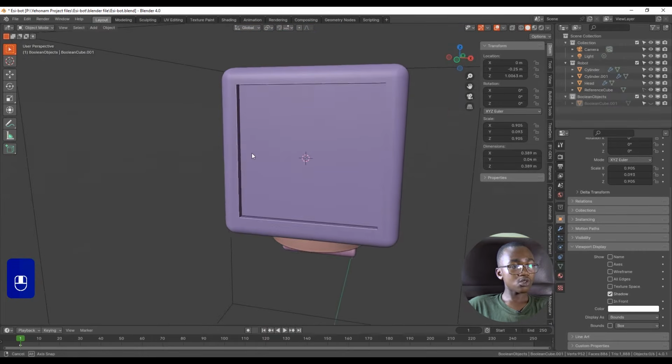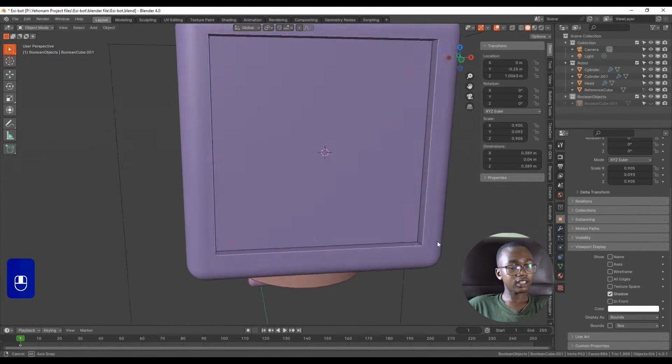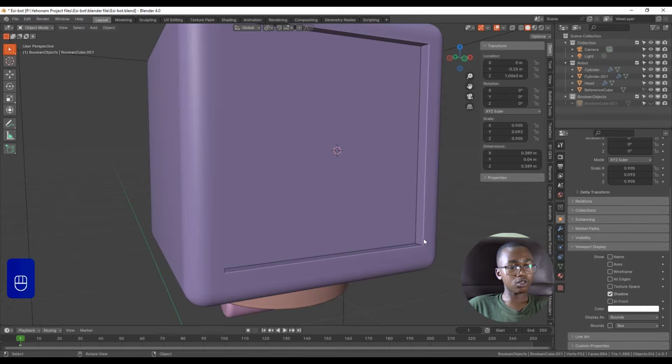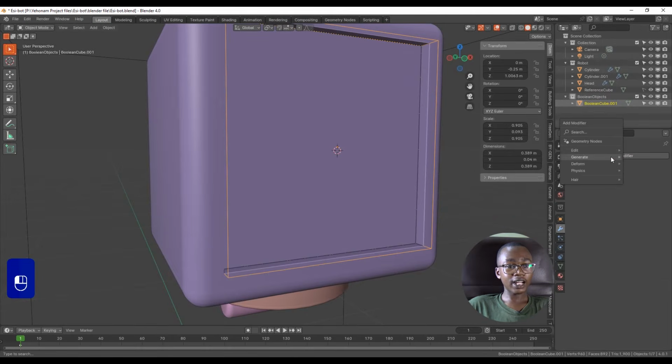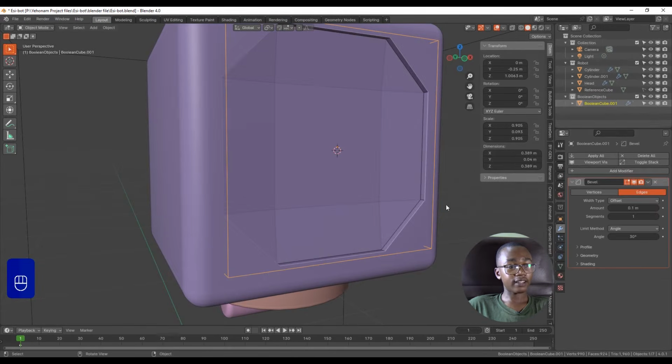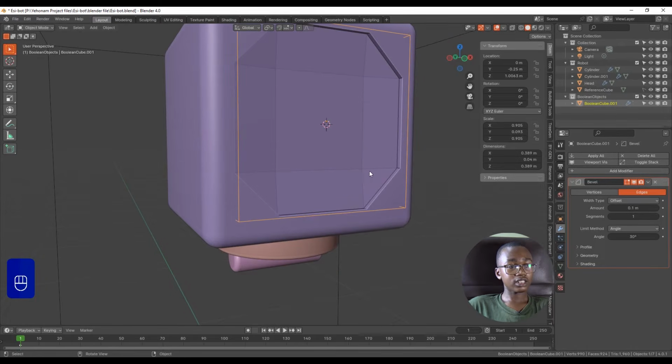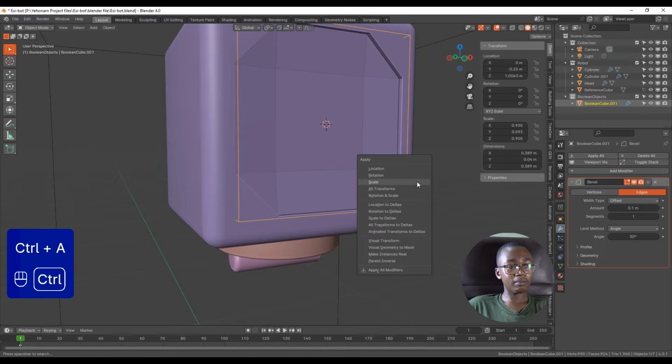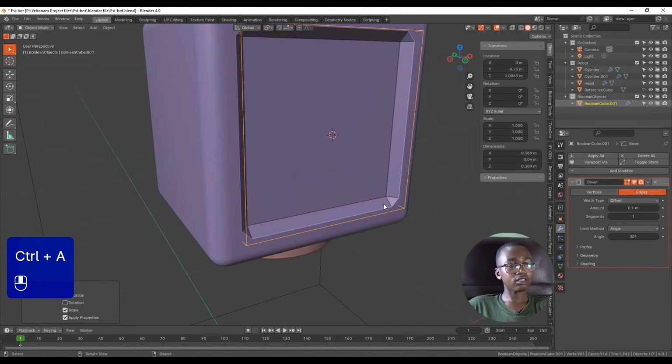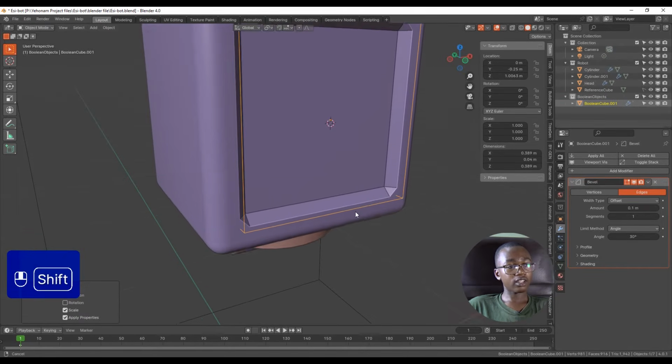I like what it's doing here, but I also like some sort of crease, you know, when it's meeting 90 degrees like this, at times it's not satisfying. It doesn't look nice. That is my personal preference. So how do we do that? You unhide it, clear the boolean cube, and we add a bevel modifier to this. You see it creates this because its scale has not been applied. So when we try applying scale, yep, that should work.